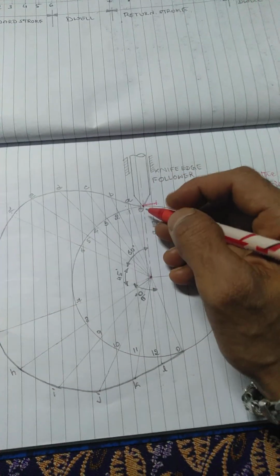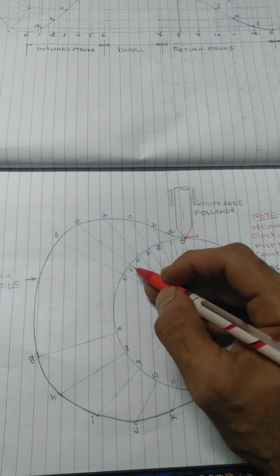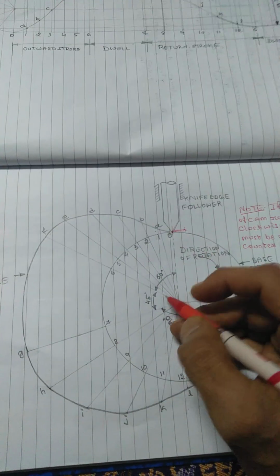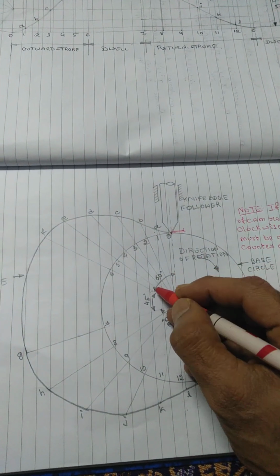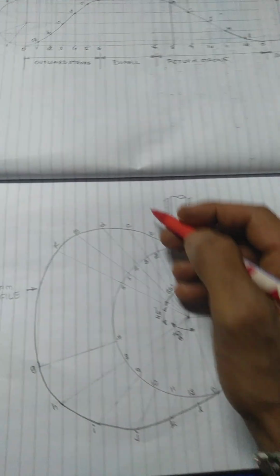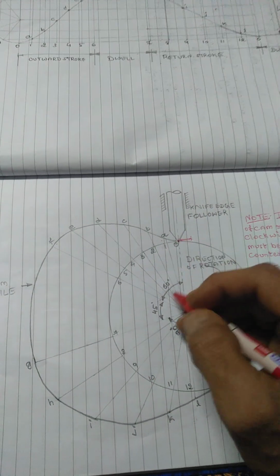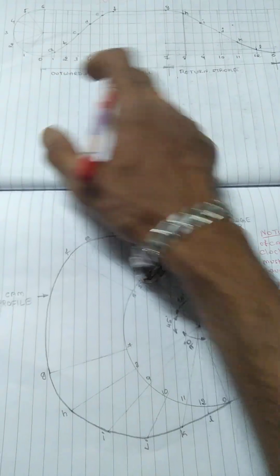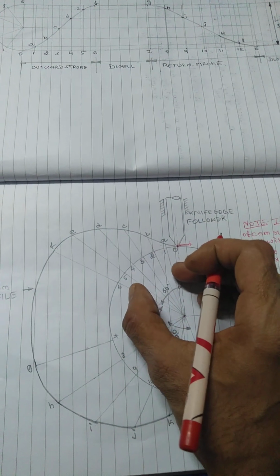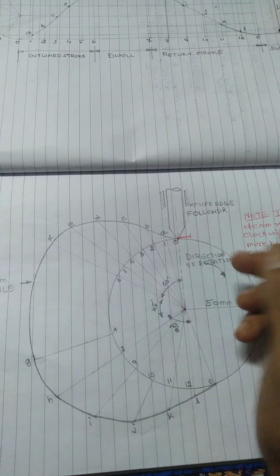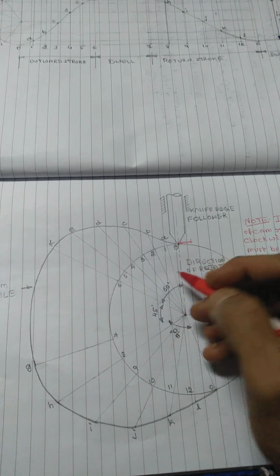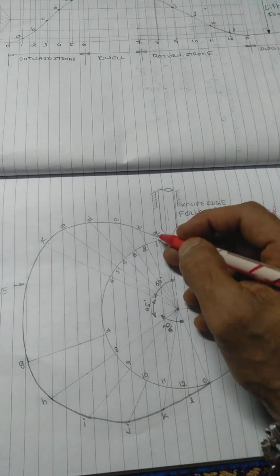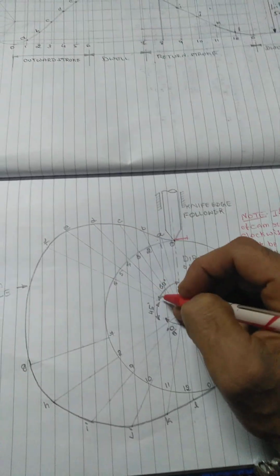Next, marking the points. First mark 60 degrees here, from here to here it is 60 degrees, and divide the 60 degrees into 6 parts, because you have taken 6 parts here. So I have divided it into 6 parts. After that, draw a smooth, light line.